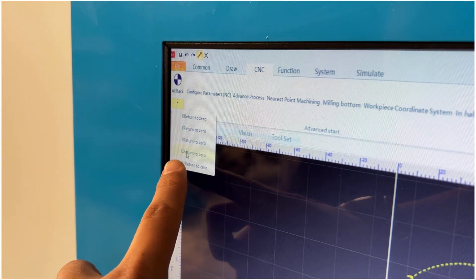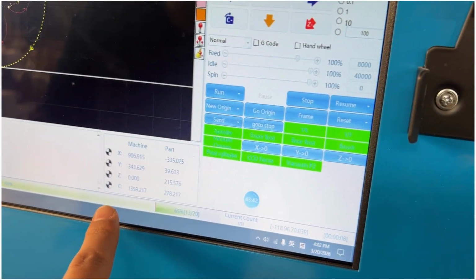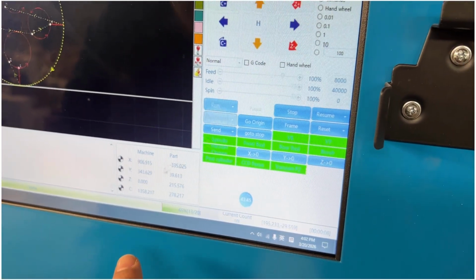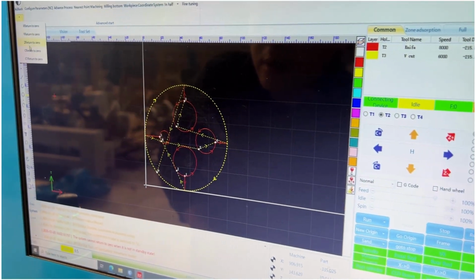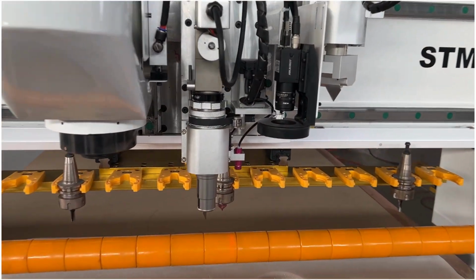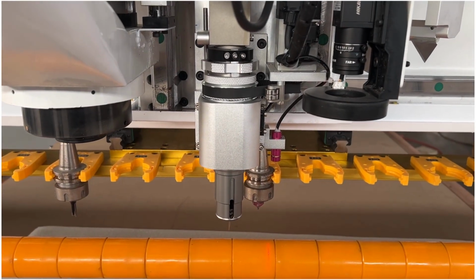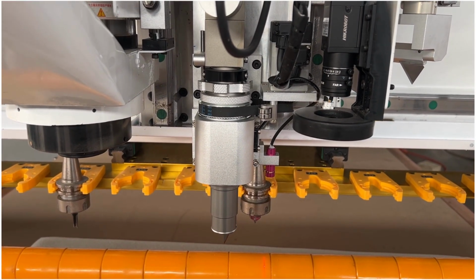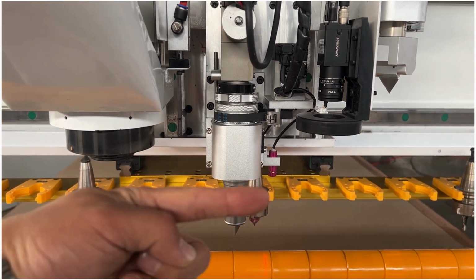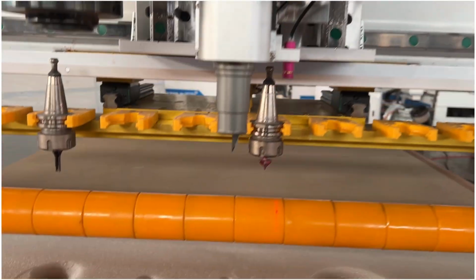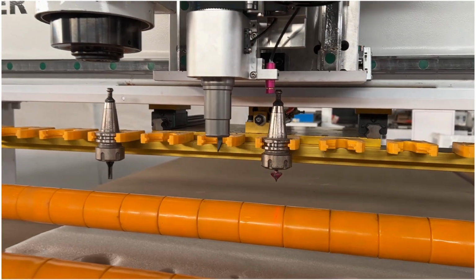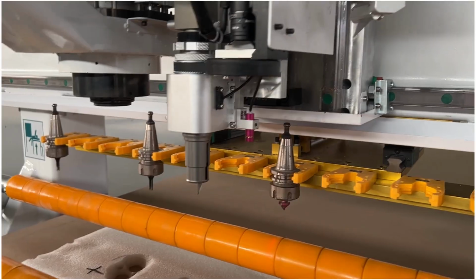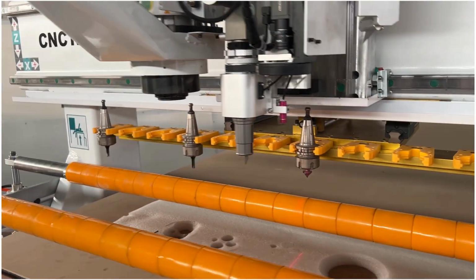In the control software, home the C-axis independently. After the C-axis returns to 0, verify that the cutting edge is oriented to the right. The tool insert replacement is now complete.